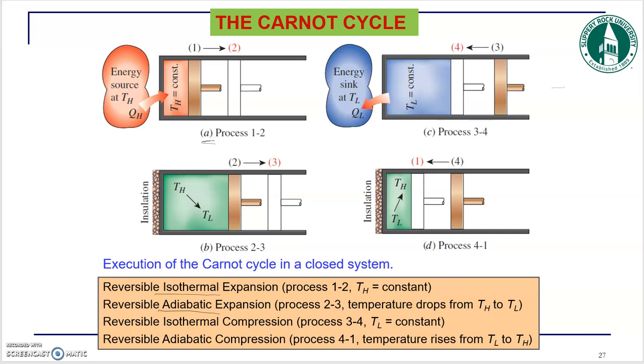This piston is pushed, so there is some work applied to your system. From state 1 to state 3, your gas is doing some work on the surroundings, right? There is a boundary work happening here by your gas. Now from state 3 to state 4, or coming back finally to state 1, which we will discuss, you are doing some work on your gas.